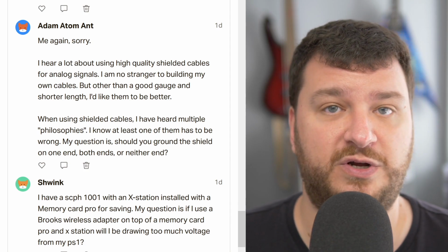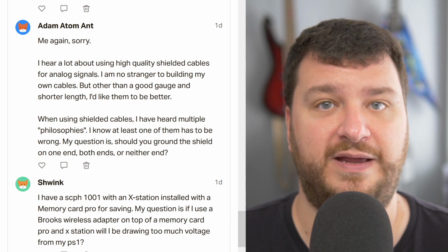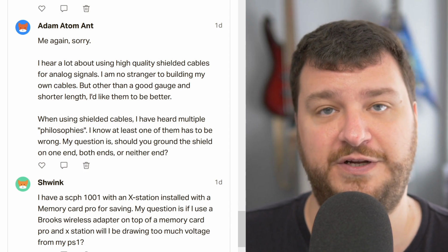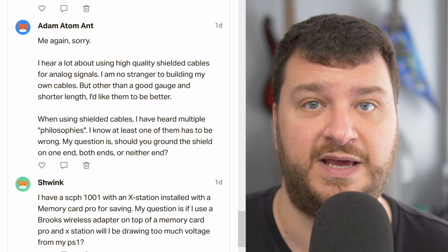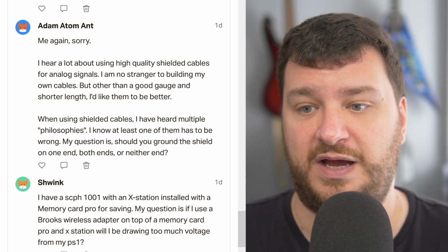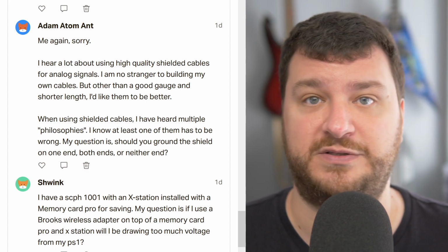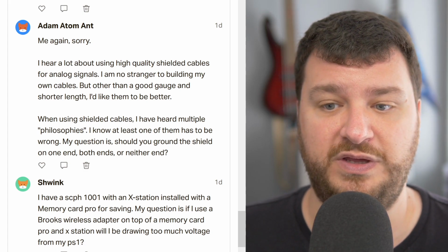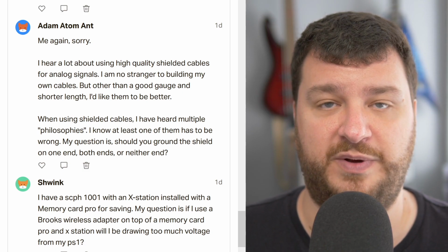Because if you're talking about a SCART cable, it's very common that each of the grounds for each of the video signals have their own separate lines. So have you connected all of those? What about the target device? What about the source device? So it really is a question that could be answered by a total setup.